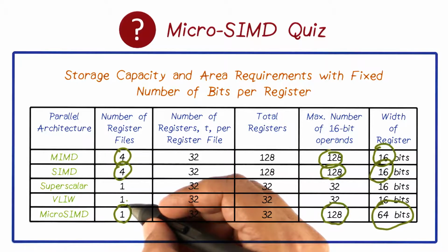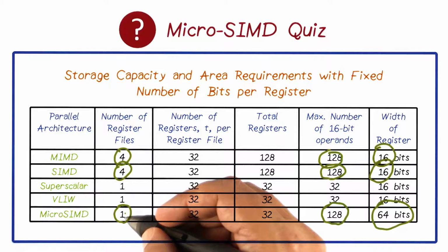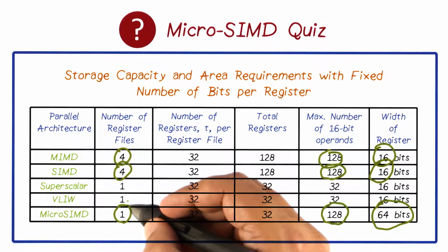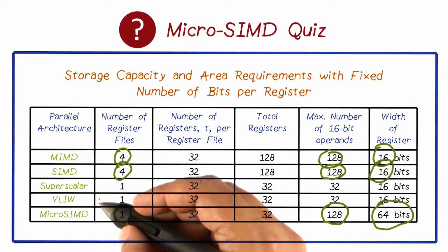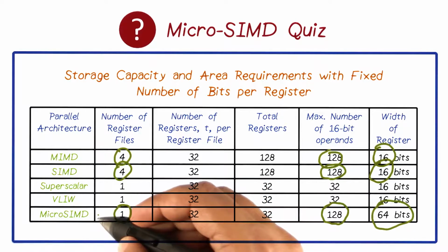In other words, in micro-SIMD, you still have just one instruction which is doing adds across the board, whereas in VLIW, in those 4 slots, you could execute 4 different kinds of instructions. So in other words, VLIW supports much more general parallelism than micro-SIMD.